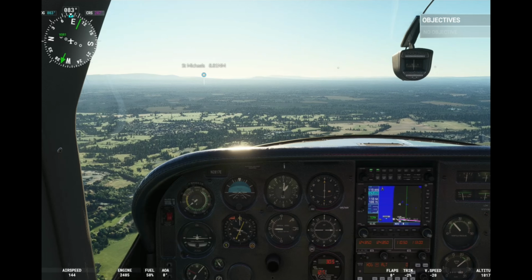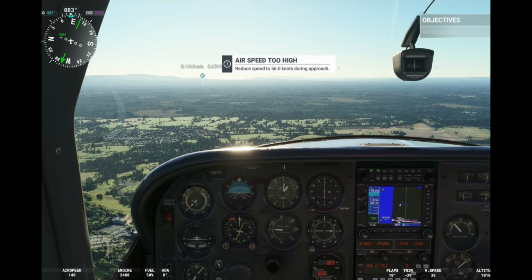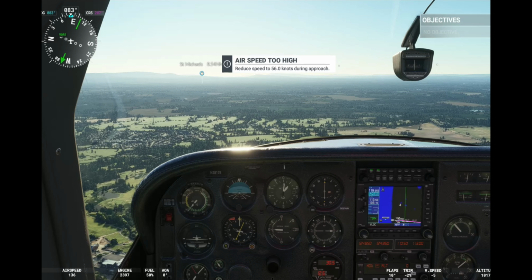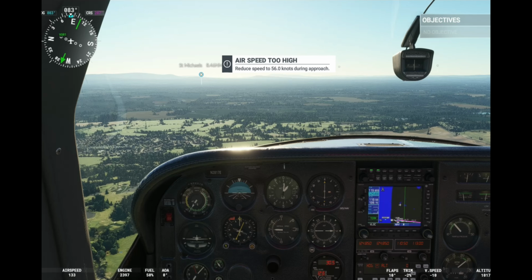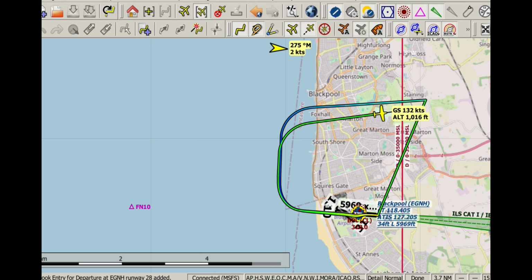green and good, and also the QFE dialed in for the airfield. C for carb heat, but make sure it's off for finals because you need full power for go around. H is for hatches and harnesses to be secured.